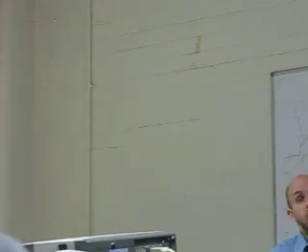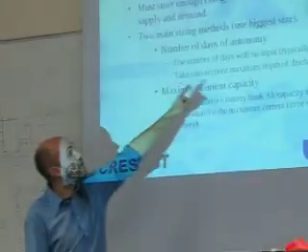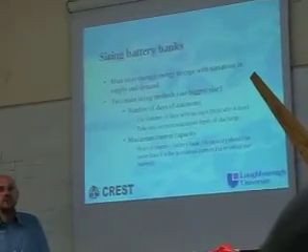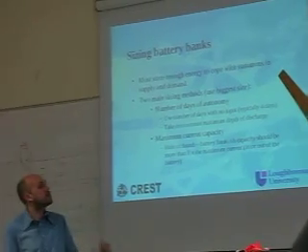There are two different methods here. I won't go into them too deeply. You either use a number of days of autonomy, which basically means you say that this system will work for 4 days or whatever with no energy coming in, and it will supply the loads, and that's how you design your battery bank. And that's how I would do a system. I would say typically 4 days, no input, and that's how I would design how big a battery I need. Generally, that works. You may have times in winter where it doesn't work, times in summer when you're wasting a lot of power.